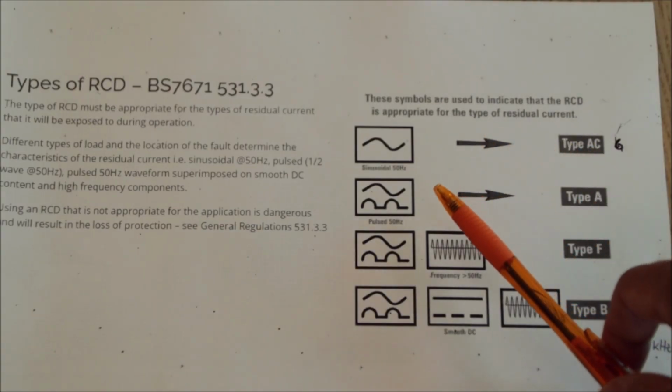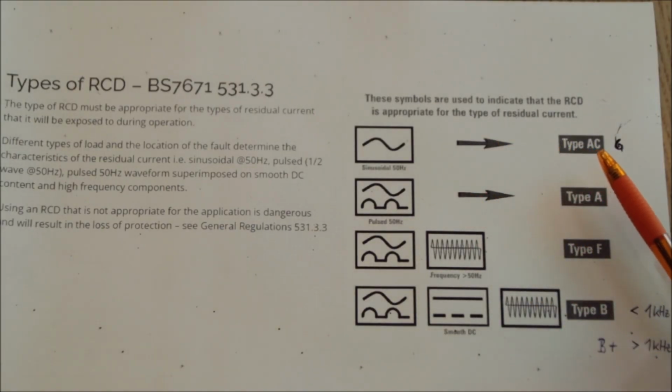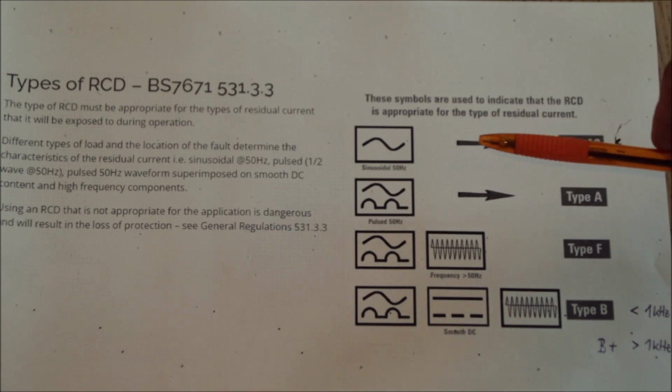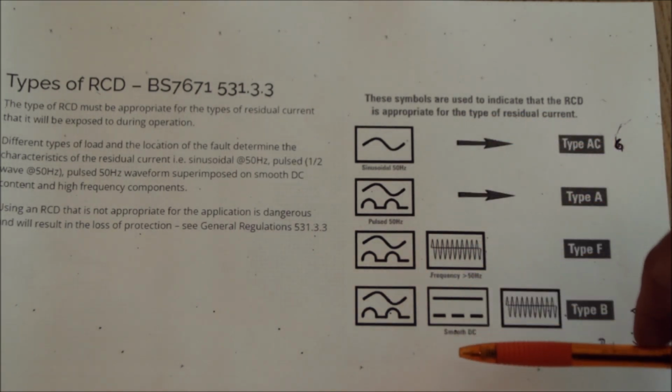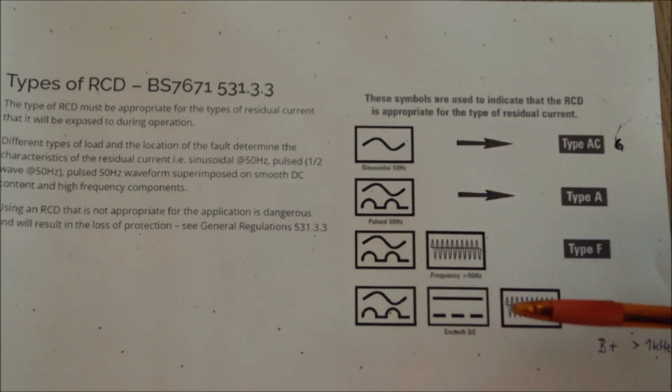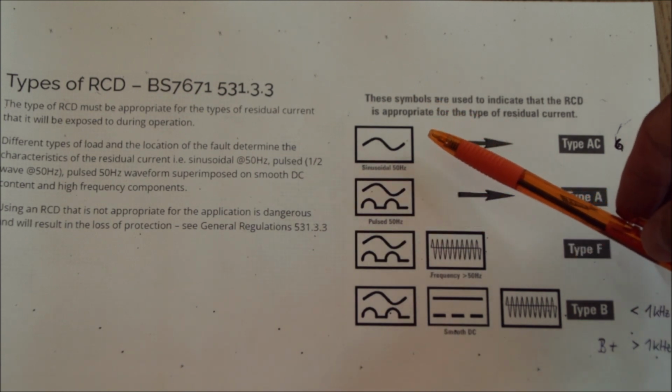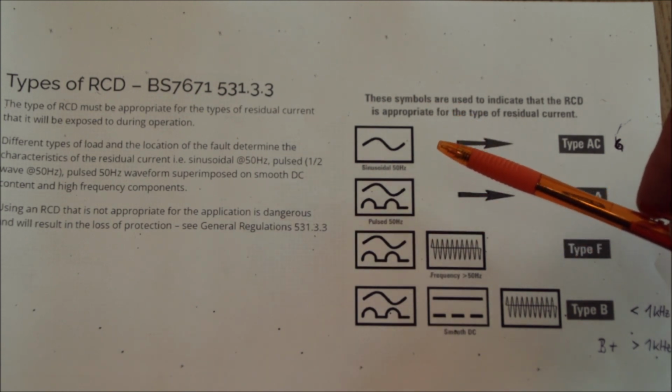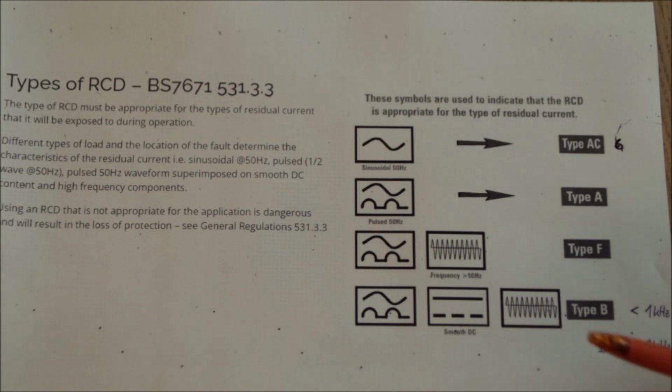So you see the basic types like the Type A, C, and some countries also have a Type G. If you start at the basic and go up to the higher level types, every type will always include the features of the previous types and then add something new, a new feature. What that means is that the device will recognize different styles of residual current.